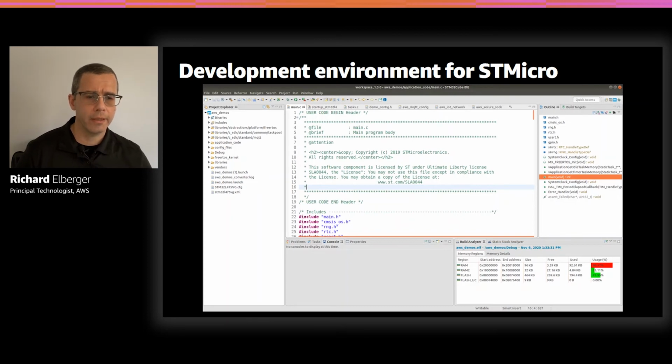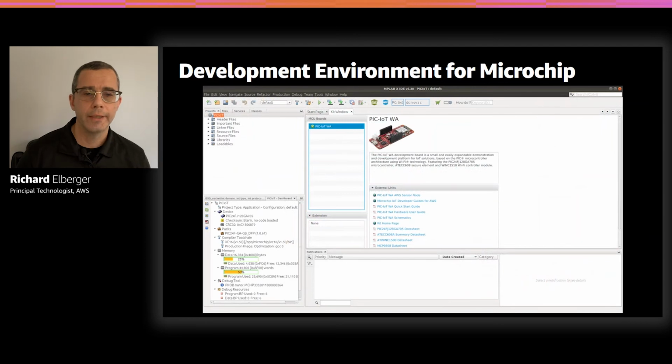The next is the MPLAB X IDE, all right? The way the files are organized in MPLAB X is a little bit different than the STM32 Cube that I just showed you. What I really like about MPLAB X is its plug-in infrastructure, and I use its data visualizer really often. It also has a FreeRTOS task analyzer or visualizer. Usually when I'm working with Microchip stuff that's ARM-based, I use Percepio or Segger tools. But with PIC, that's a little hard, so I rely on the tool here. I just hope that they take a look at the functionalities that are in FreeRTOS a little bit deeper here. So, room for improvement, I would say.